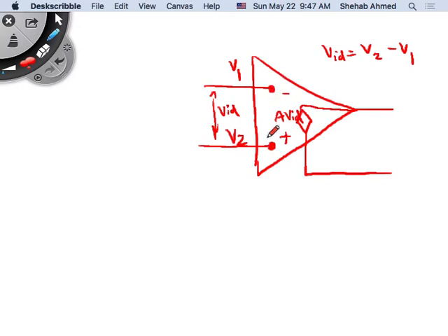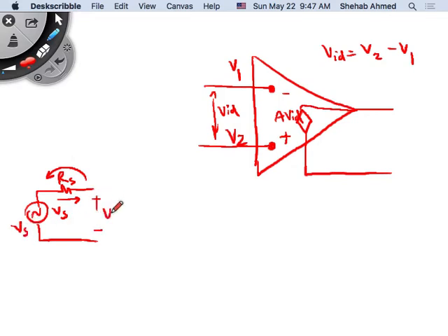The equivalent circuit model is such that I would like to do something useful for me, right? So I designed this op-amp. Remember in the last chapter we were designing the amplifier and selecting values of resistors to make something interesting happen. What was interesting was that at the input, if I have Vs and the equivalent circuit of the sensor looking like this, I do not draw any current or minimal current, so that I don't have a voltage drop here, so that at my input of my amplifier, I see V input equal to Vs.